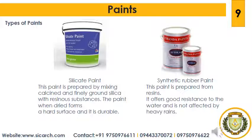So the silicate paint can be directly applied on brick, plaster or concrete surfaces. These surfaces should be made wet before the paint is applied. So 2 to 3 coats of silicate paint are recommended and it is not necessary to have a priming coat. The tool which is used to apply silicate paint should be immediately cleaned with water after use. The surfaces should not be painted in silicate paint in hot weather.